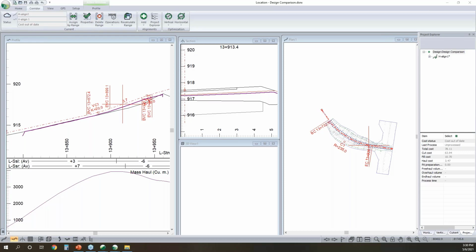And for this question, I should have been more clear about what I was referring to. Just to clarify, topo survey is what the area looked like prior to the excavation. In this case, our topo survey is both the survey for original ground and the survey for our as-built, the final survey or in-progress survey.